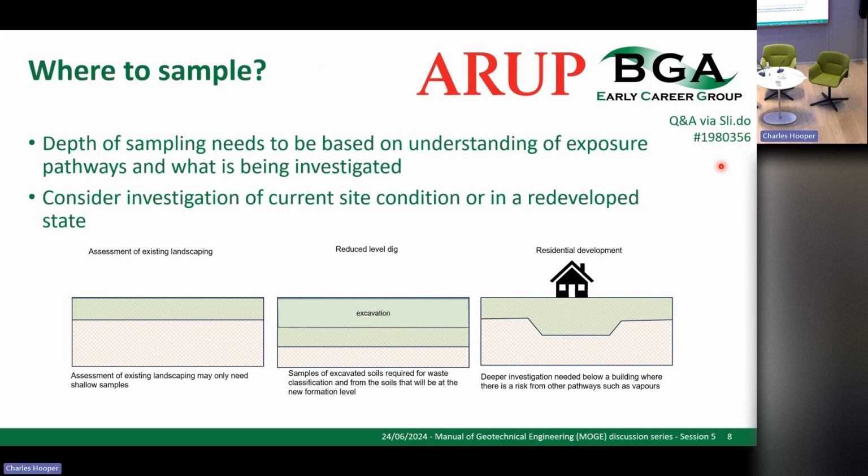So we would be focusing on that upper surface of the soil. Typically, we would say half a meter if you're not going to be digging holes within it. But you could potentially reduce it down further, particularly if you've got areas of landscaping that are more densely vegetated. So by reducing that level of depth, you could maybe get a lot more shallow positions in rather than a few deeper positions, and give much better coverage to your site than if you were to just go with a default, say, 5-meter window sample across that whole area.